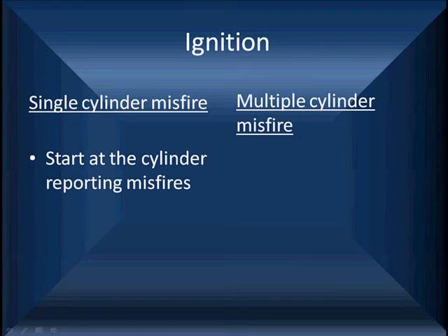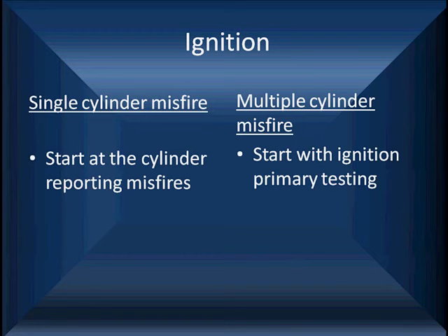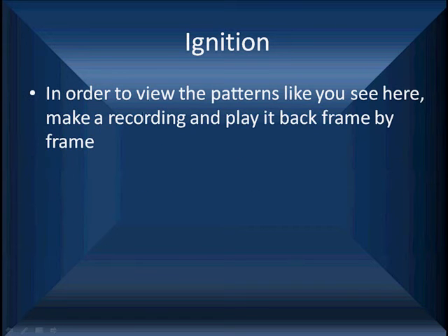Now we're going to start down through and look at our single cylinder misfires as well as multiple cylinder misfires. Now we're going to start with our primary ignition. We could have started other places, and you can jump to another part of the program if you want to start with fuel delivery, fuel control. But let's talk about the ignition.